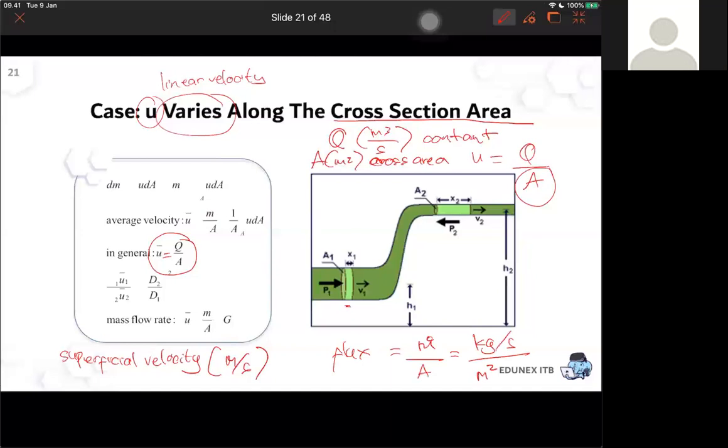Sir, so here you would identify the m dot divided by the cross-sectional area of where the pipe is? Sorry again? So over here you would calculate, for example, the volumetric flow rate first, multiplied by the rho of the fluid. Then the area would be which part do you want to calculate the flux in, which area is it? Yes, the cross-sectional area of the pipe, or of the fluid. Yeah, yes. So for example, if